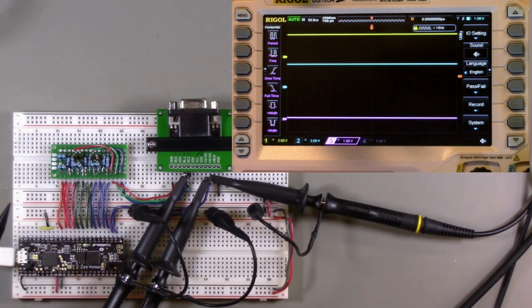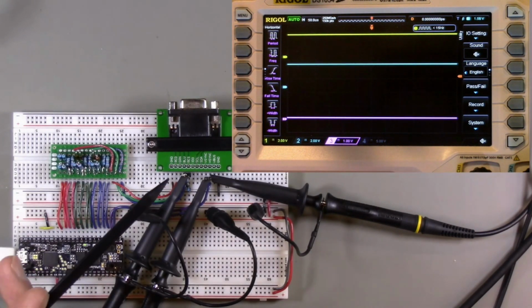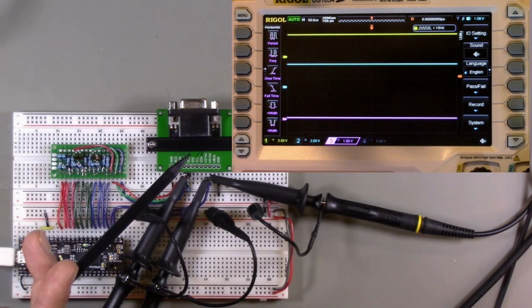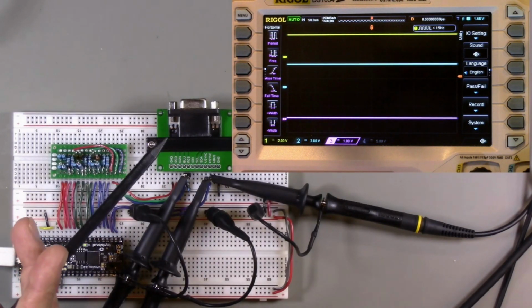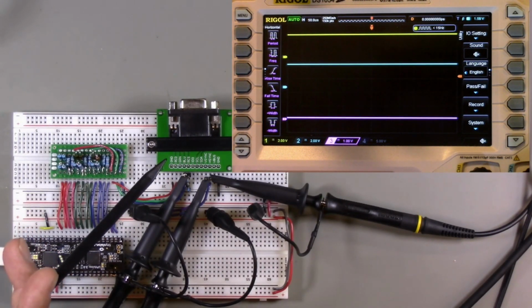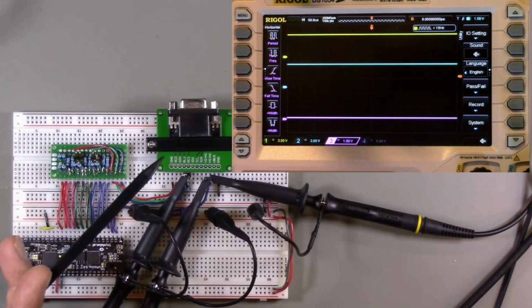Alright, so here's our test setup. Here's the Upduino board. This board is our resistor DAC for the red, green, and blue color signals that are 4 bits each as they come out of the FPGA, but then they're mixed together to produce our analog color voltages, and then these pins produce the H-sync and V-sync signals. The color signals and the sync signals are going to this VGA breakout board. It's not connected to a monitor right now. I just want to test to see if the signals that we're generating look right.